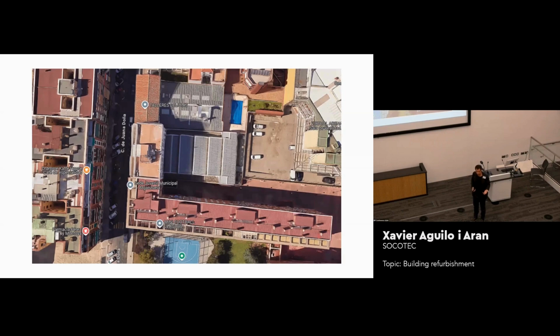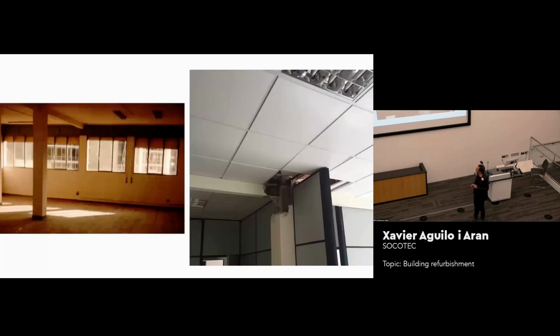Madrid is a very dry city, and what we tried to do was to work with the evaporation cooling effect. So if you spray water, the water evaporates, and in the process of evaporating and changing phase, takes heat from the air, and then you feel much better. And because there is low humidity in Madrid, when you increase the humidity, you are more comfortable, right?